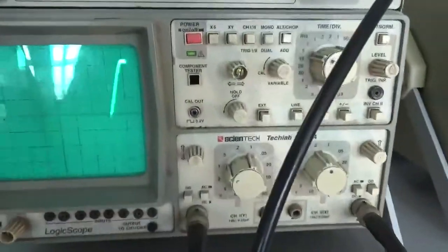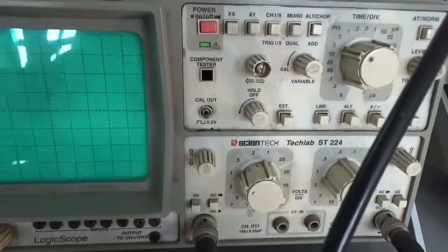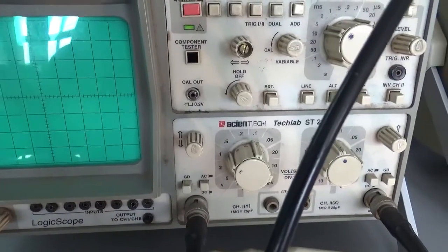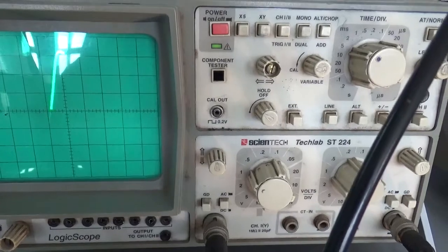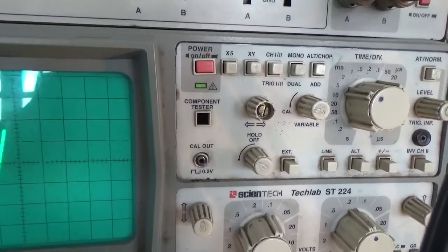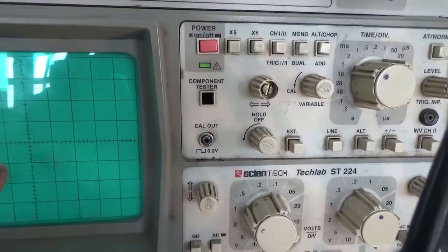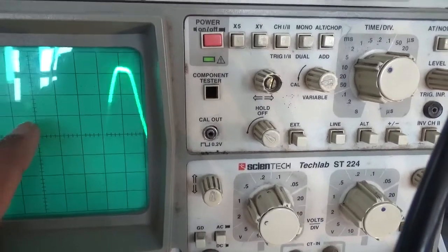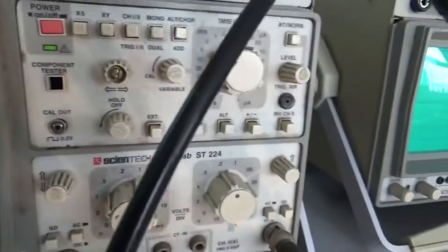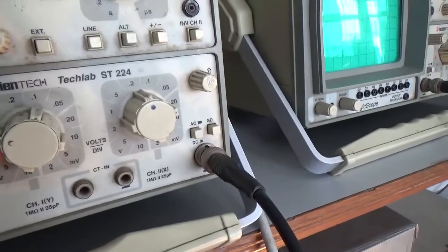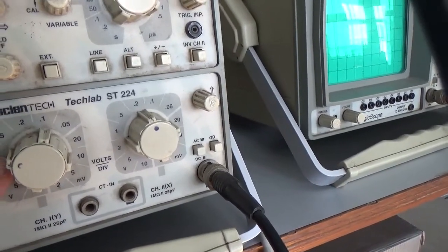Let me go to the CRO. This is the supply voltage, which is in fact connected to the output point. When my firing angle alpha is 0, my output and input both will be the same. Now let us count the number of units covered for the measurement of the peak. 1, 2, 3, 3.2. So 3.2 into 1 is 3.2 volt only.